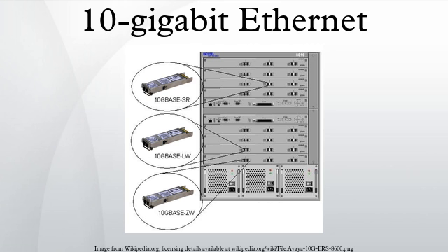10GBASE-LX4 also allows a range of 10 km over SMF. For MMF links the WDM output needs to be coupled through a SMF offset launch mode conditioning patch cord. This is explained in subclauses 53.6 and 38.11.4 of the IEEE 802.3 spec.